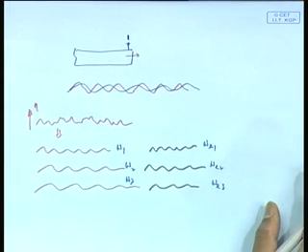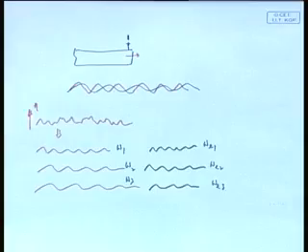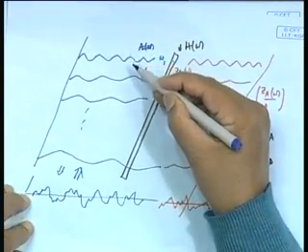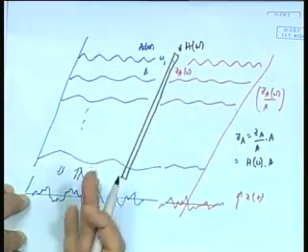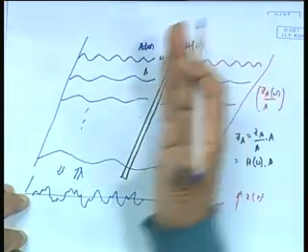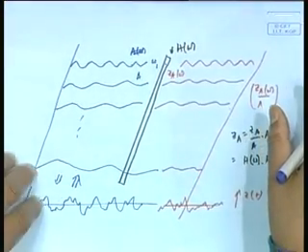Remember, the one that ship is feeling is not the omegas. So what happened when I broke down this spectrum to these omegas, that is not what the ship is responding to. So I have to take one more step: I have to first break it down, then change this to omega E, then filter to this output. So that is why in forward speed I have this problem.